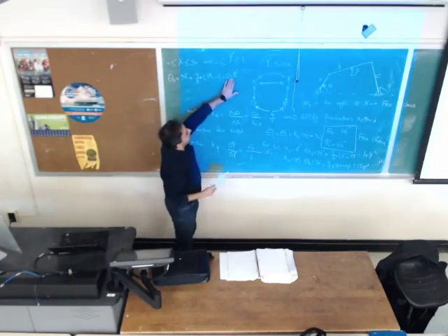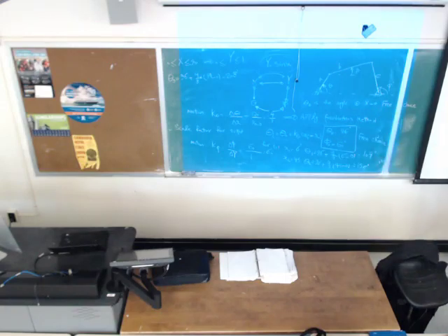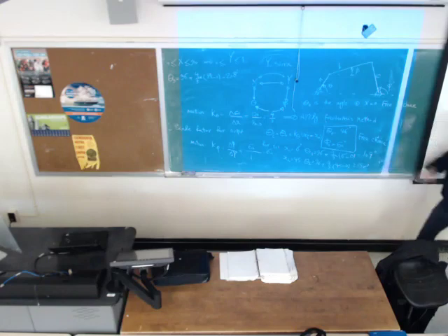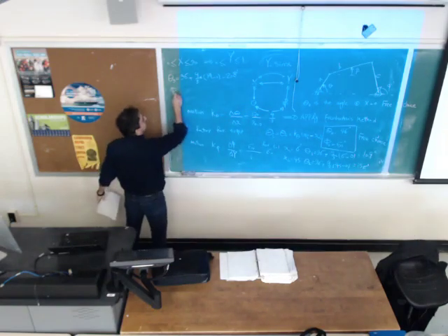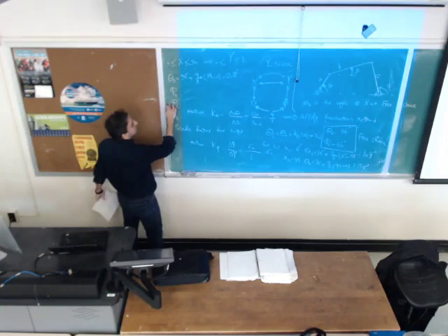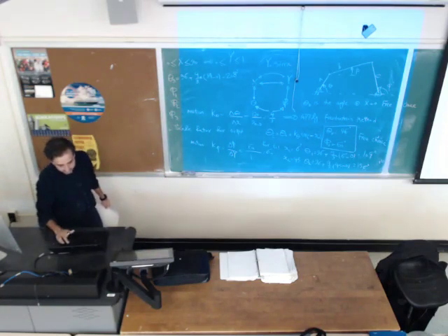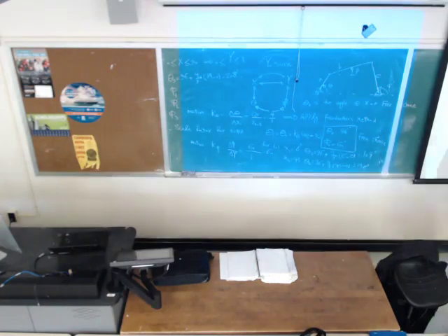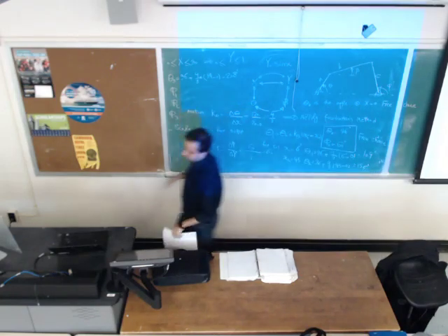So now I know that when the input link is moving from 0 to 90, when it's at 6 degrees on this guy, the theta corresponding to that should be 104. When it's at 45 degrees, the theta corresponding to that is 156, and when it's at 84, the angle is going to be 208. If I find phi1, phi2, and phi3, then I'm going to have theta 1, phi1, theta 2, phi2, theta 3, and phi3 back into this set of equations. I have theta 1, phi1, theta 2, phi2, theta 3, phi3. I'll solve for theta 1, k1, k2, k3.